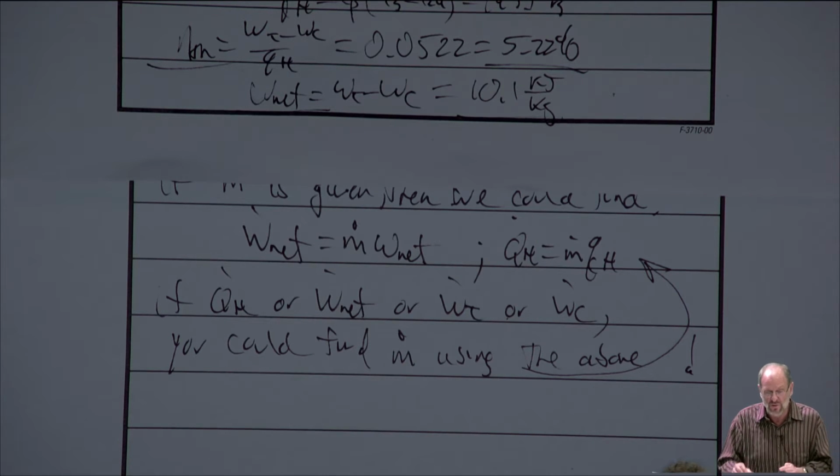Now, for water or R134A, we've got really good tables, right? Well, mostly really good tables. We have superheat tables, so that's everything to the right of the saturated vapor. We've got mixture tables or saturation tables, so that's where we would use quality in order to find the thermodynamic properties for these two-phase mixtures. We also have compressed liquid tables, although we only have a water compressed liquid table. There's not one for R134A, and the property table for compressed liquid water starts at such a high pressure that it's practically useless. At least to us, it's practically useless.